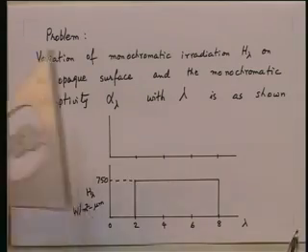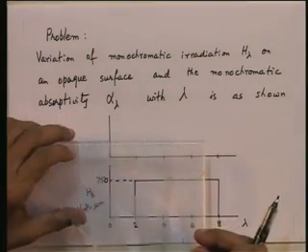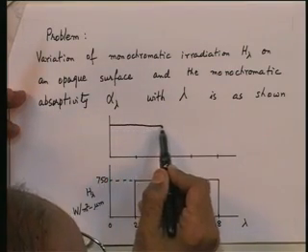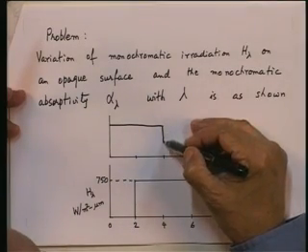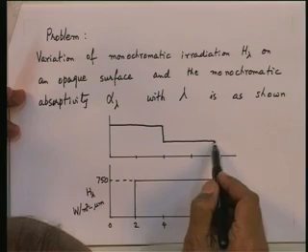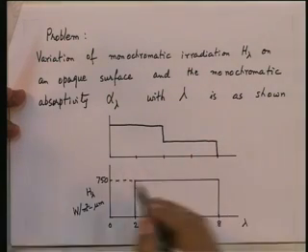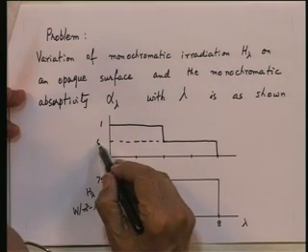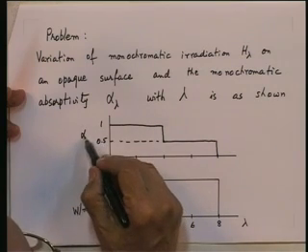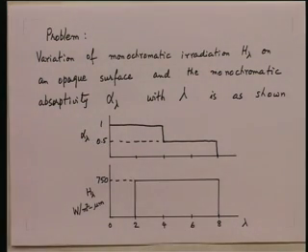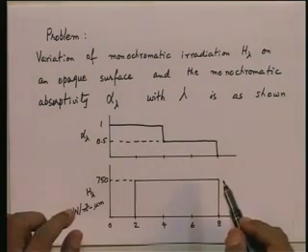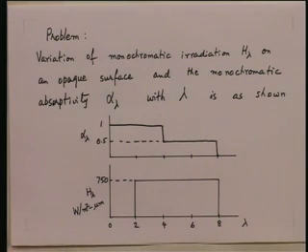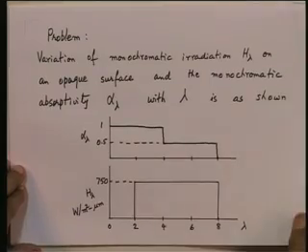And the alpha lambda varies like this, 1 comes down to 0.5, then is 0.5, then is 0. So, the variation of alpha lambda is, this is 1, this is 0.5. So, alpha lambda is 1 from 0 to 4 microns and 0.5 from 4 to 8 microns, thereafter it is 0. Okay. So, this is the variation which is given.